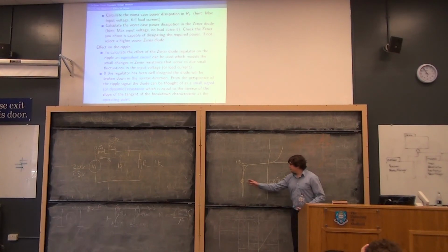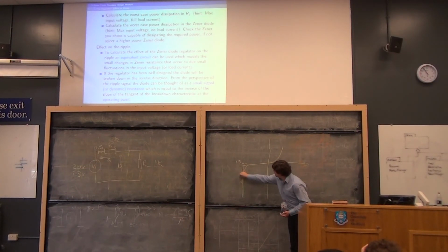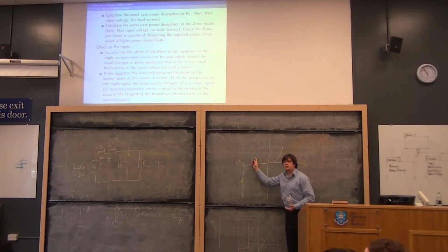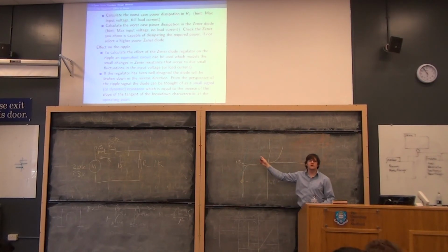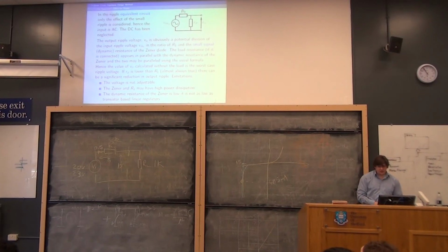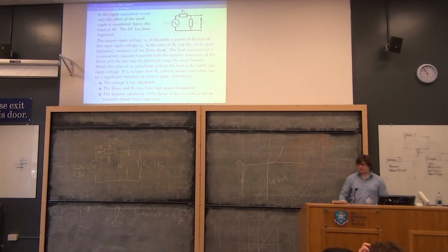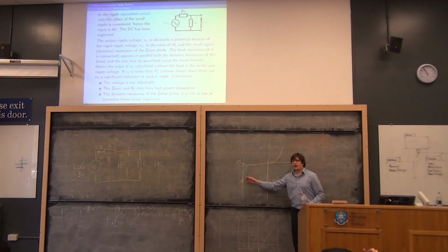Now, strictly speaking, the slope is a curve, and the curve does not have a constant gradient. If we drew the tangent, say we were here, the tangent could be across there, but if we're here, the tangent would be across there. So we would end up with different values, or different inverse values, of dynamic resistance. And it turns out that the whole circuit can be reduced to a potential divider, because I really like potential dividers and they're dead simple. So we're saying RD is the inverse of the slope of this line at some particular current.